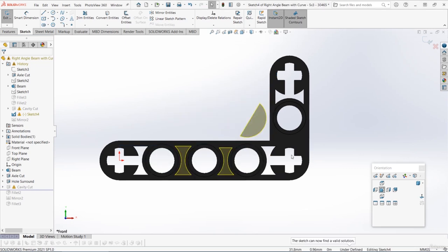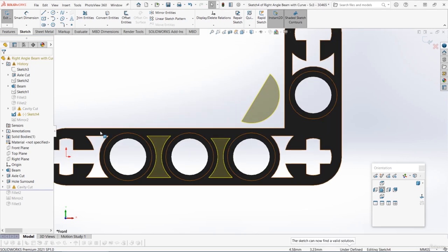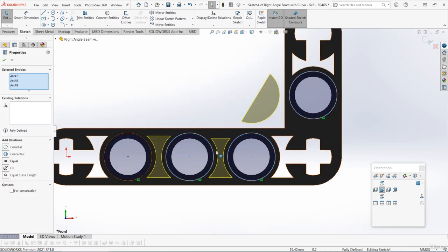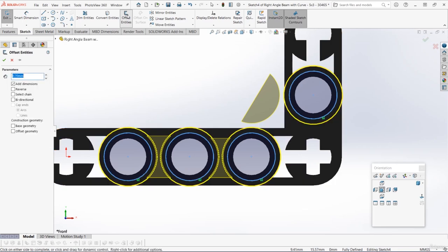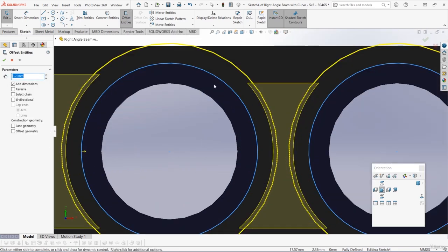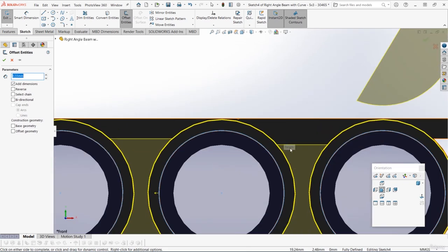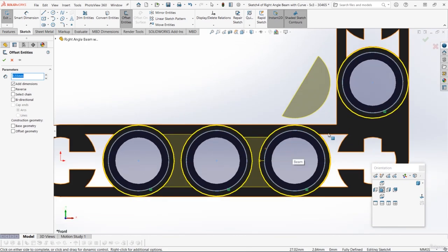So starting again from scratch, firstly, if you remember, we offset the circular lines of the existing hole ribs. So let's select the outer edges of all 4 of these holes. Let's convert them first, and then select those 4 converted circles, and then let's offset those circles. We just converted them first because sometimes offsetting directly like this doesn't quite work when you've got multiple edges selected. Then let's offset 0.55 millimeters.